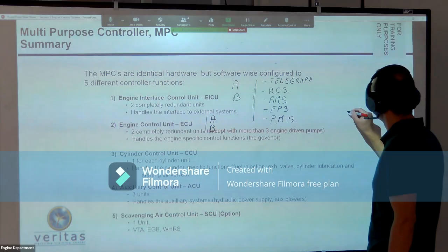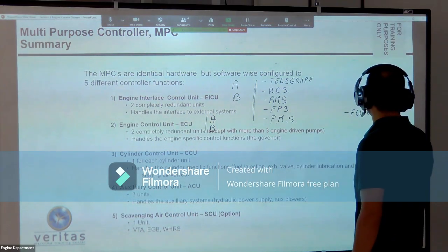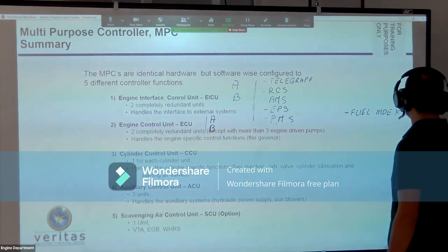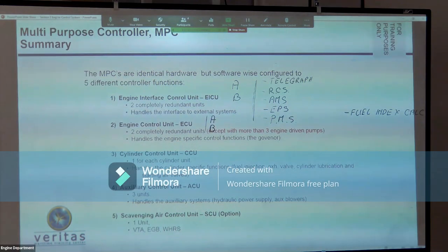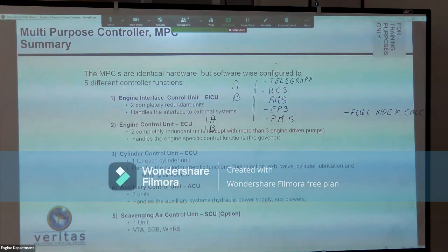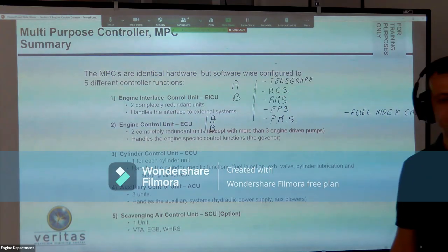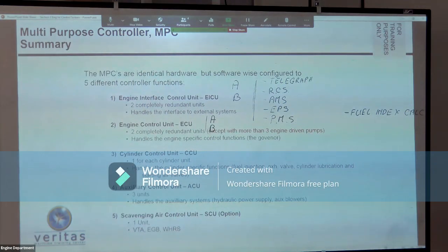So it's fuel index calculation. According to the sailing area of the vessel, NOx mode, in case we are sailing in an emission control area, or economy mode outside of the area, as we saw yesterday, the heat released by the engine depends on the timing of the injection.